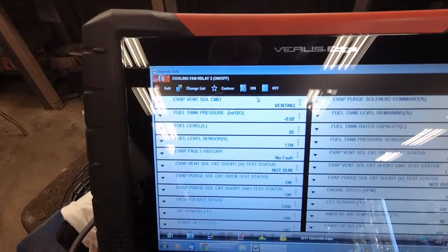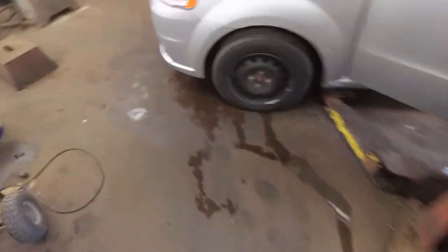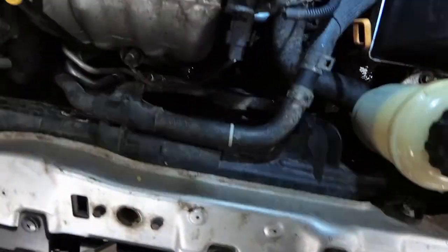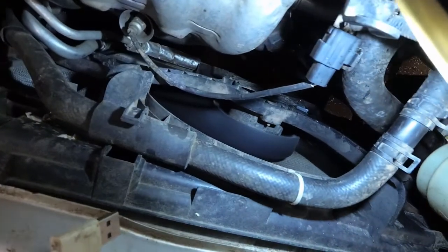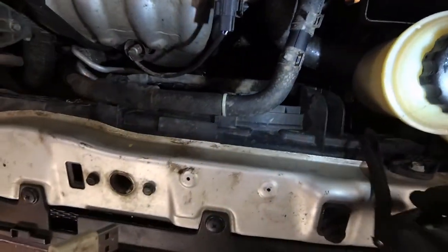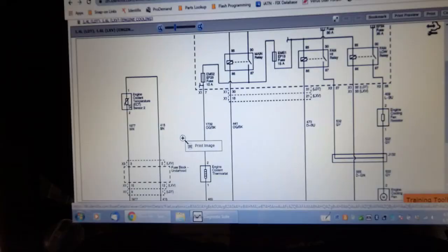There is another radiator cooling fan relay. I wonder if that one makes a difference. So radiator cooling fan relay 2 commands the cooling fan on, and it runs. It appears on high. So I wonder if there's two speeds to this thing, and one speed has failed. So there's a dropping resistor or something. I'm going to have to look at the schematic.